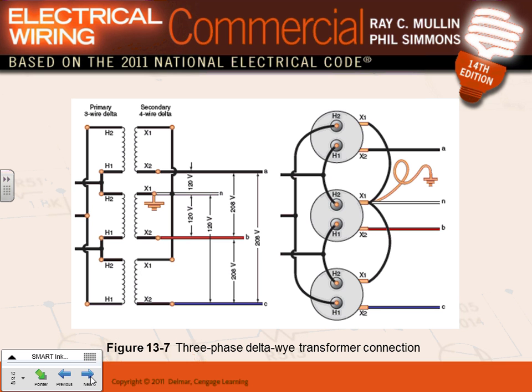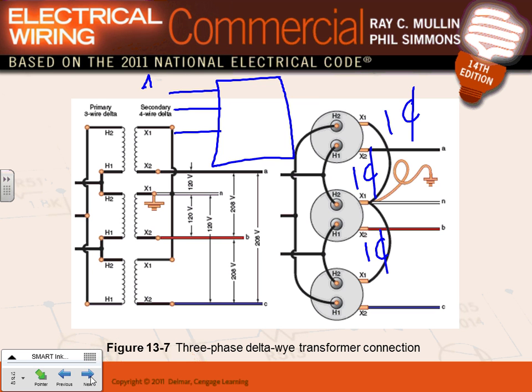Okay, so we got the Y. This is how you get it from the utility type. As engineers, Aaron, my friend, when we ask for this, we don't like this. We ask for a 3-phase transformer. These are three single-phase transformers, right? Coming from the utility. When you have a commercial building, typically they don't give you three single-phase transformers. What they do is they give you a big fat transformer like this, right? And from here, that will be phase A, phase B, phase C, and from here will be phase A, phase B, and phase C, and a neutral.